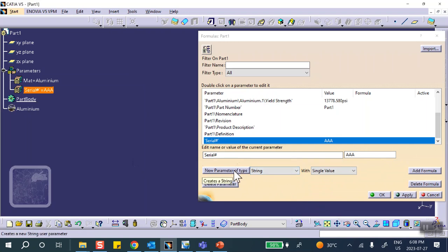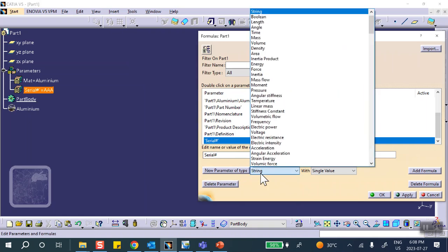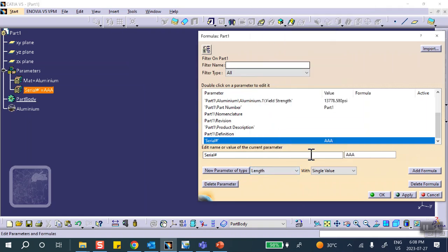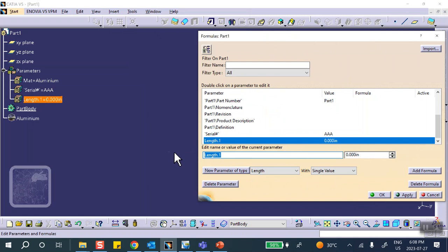So let's go ahead here, type length, new parameter. Let's start with L, and I said for L, I'm going to use 10. The first row says 10. Another one, B, that's the size on the top, and the value of B in the table says 8. I might as well use that.